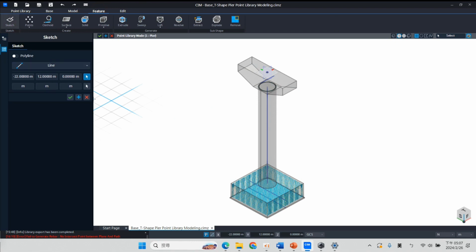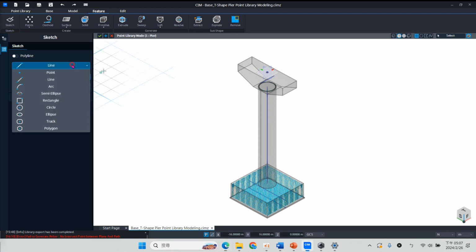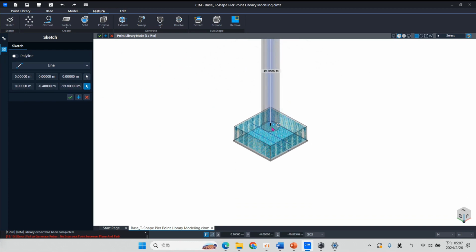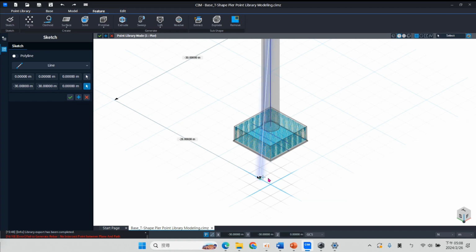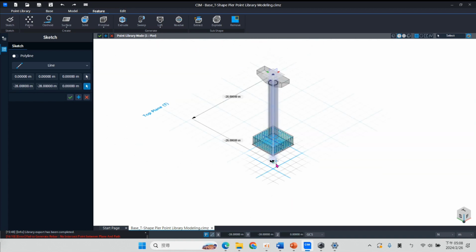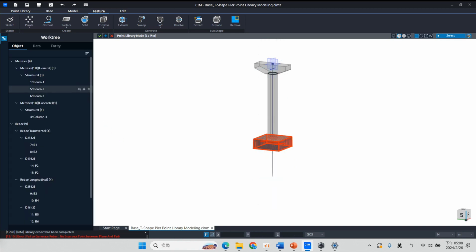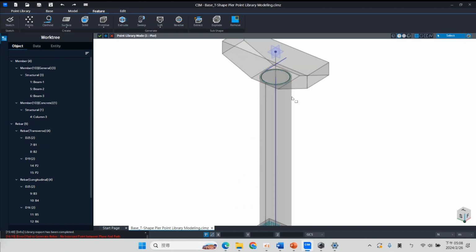So you want to create a sketch line here with a line of 2 points starting from the middle top to, so you can click F and you will be free to click on the vertical part. Okay, and this will be important to array this rebar.